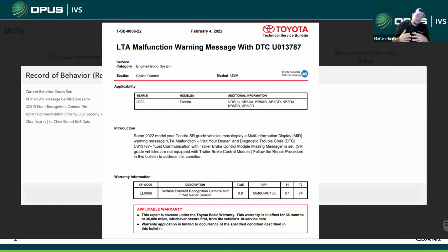So the message behind that is double check your parts. I've had a lot of wrong model parts. I've had parts that were not destined for the United States be in a TMS USA box, but be a part for a car that was supposed to be built in Indonesia or somewhere like that. In this example, I spent a lot of time because I didn't check the part number of the camera. It took it, it worked, and did all the calibrations, but it had the wrong camera in it. If you do get the right camera, it should need just a software update.